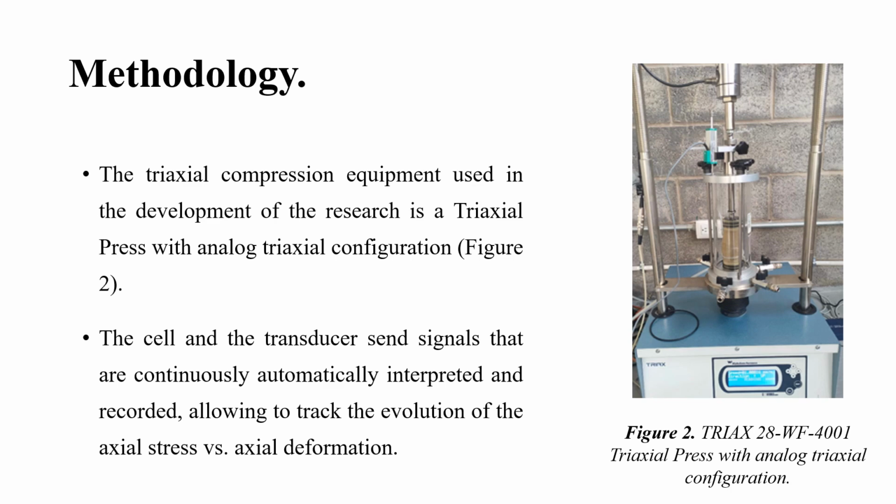In order to stress the soil, we have used the triaxial compression device that is on the screen in figure 2. This triaxial compression device is able to record and control the stresses and mainly the strains that the soil is being subjected to. On this screen we can see the sample that has been put inside the triaxial compression device.